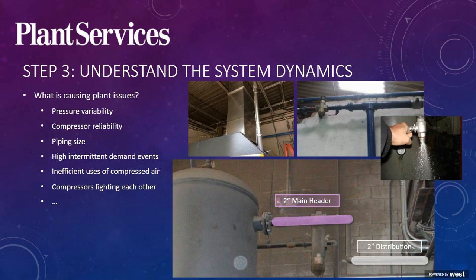Also, the picture at the top right shows a T coming straight down from the pipe. That next picture there, clockwise down, shows water at the connection point below this particular T. So this might explain product quality problems at the point of use. Further, the bottom picture shows piping after a dry tank. This pipe could be amply sized for what they're using, but it could also be significantly undersized. So it all depends on the flow profile.